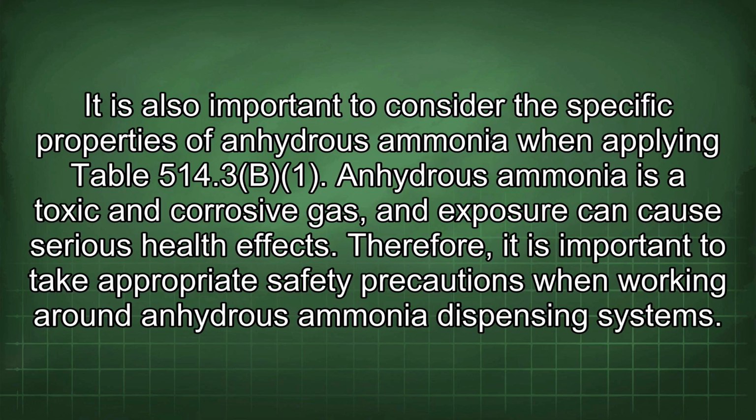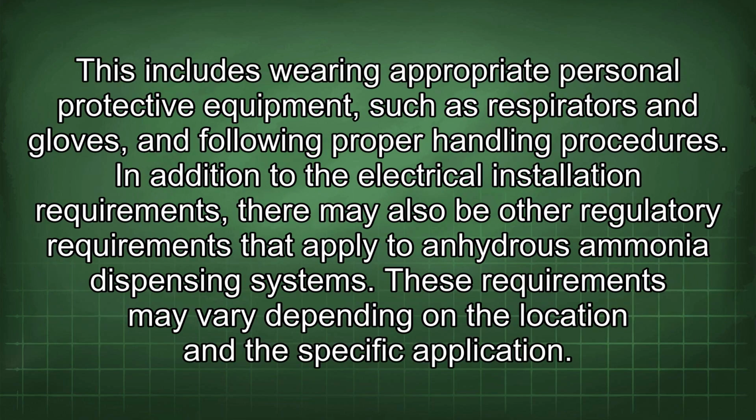It is also important to consider the specific properties of anhydrous ammonia when applying Table 514.3(B)(1). Anhydrous ammonia is a toxic and corrosive gas, and exposure can cause serious health effects. Therefore, it is important to take appropriate safety precautions when working around anhydrous ammonia dispensing systems. This includes wearing appropriate personal protective equipment, such as respirators and gloves, and following proper handling procedures.